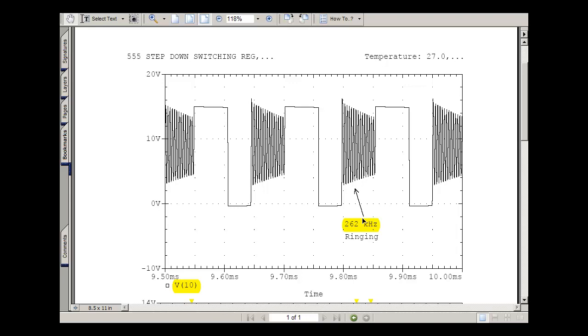I was wondering, where's that coming from? Well, I have an inductor of 1 millihenry, and that inductor sees some capacitance looking back into the circuit. At this frequency, the large capacitor we have for the load, the 50 microfarads, looks like a short circuit. But across the diode, when you reverse bias it with about 10 volts, you get about 250 picofarads of capacitance.